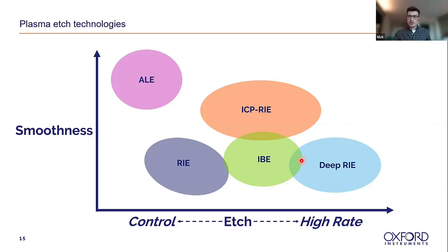So we can see how they all kind of fall down in this little table here. I've also kind of cheated and split reactive ion etching into a few different categories because RIE is a very diverse and versatile tool. There are a few different flavors, but you can broadly see that if you want a very high etch rate, you're best to use a reactive ion etch process.